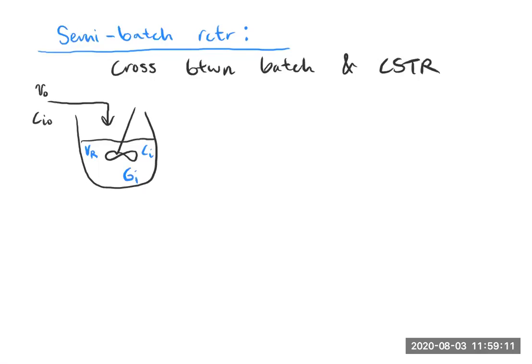So if we go back to the design equation and our terms, I won't always write this out, but for now, let's just keep that there as a reference. What do we have coming in? Well, remember, all of our units here are moles per time. So if we want to figure out what our in term is, we have some kind of molar flow rate. I didn't write it that way. I could have had Fi naught here.